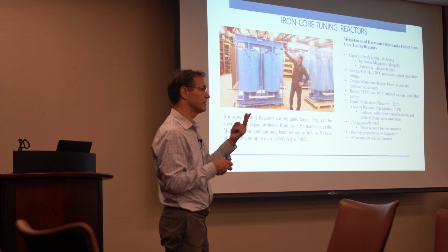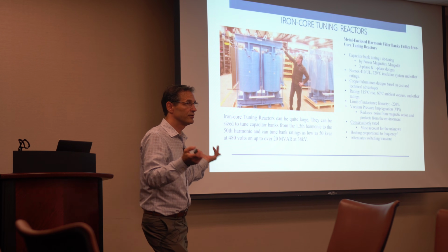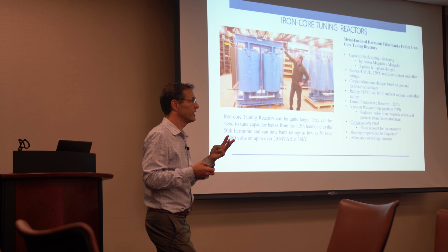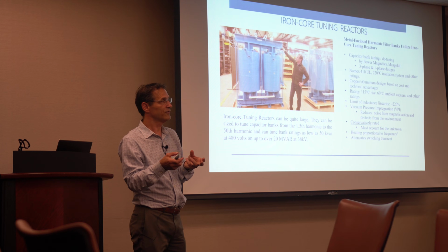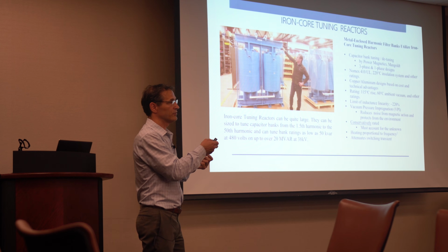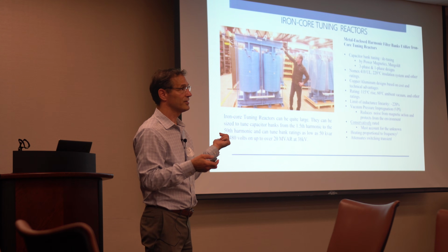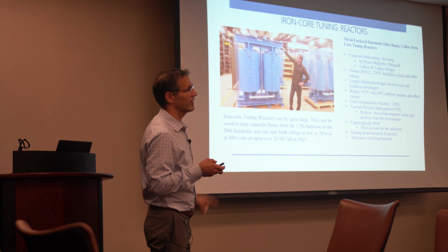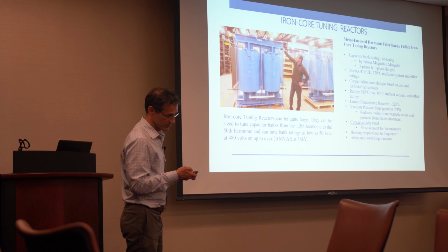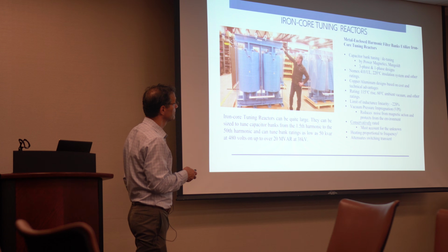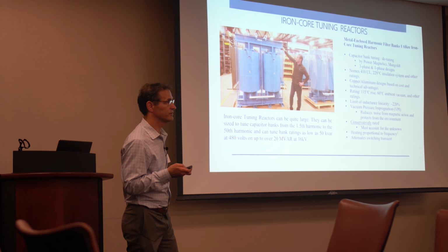You still have the other two phases, and if it's a multi-stage bank, say 30 megavars, and you have three 10 megavar banks, you're adding in these iron core reactors on every phase, and you're wiring those in. So that's the cost. The capacitors haven't really changed, not that much, just a little bit. The reactors are where the cost is. So it's a very, very expensive device, and if not properly designed, will be a major headache.